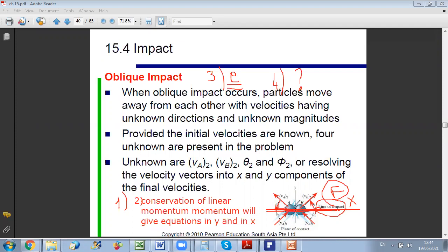This means what? This means that along Y, we don't have any force between the 2 particles. So because we don't have forces acting in Y, no impulsive forces acting in Y, then the Y velocities will not change. Yani VAy at state 1 will remain the same. So the force relation, if you want, you can write VAy at state 1 is equal to VAy at state 2.